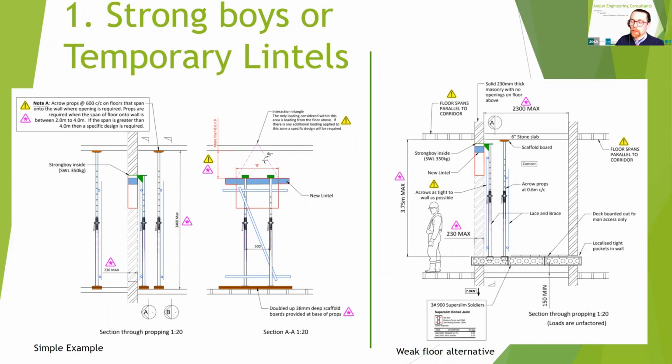load. That's very important, that there's a good contact between the top of the beam that you installed and the soffit of the wall that it's taking loading from. That's essential because when you take the wall away from the bottom, we don't want any movement onto the beam as the wall sags onto the beam and loads the beam essentially. So it's important that we dry pack to make sure it can take the load. Once that beam is taking the load, this temporary support can be removed and then the wall fully demolished to create that full opening. And that's the process in a nutshell, really.